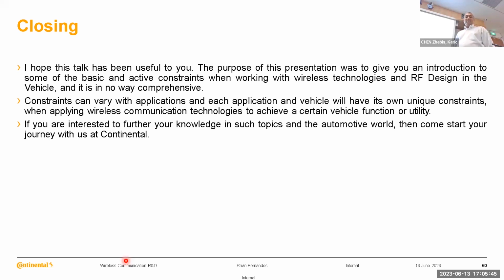Absolutely. There's very little we can do on the automotive side, because at the end of the day, GPS is designed as a function where there is a very high power transmitter high in the orbit, and a very high sensitivity receiver in the device. That receiver receives signals from at least 3 different satellites, knowing their position in the sky and their time of flight, and then makes an estimation of the position on the Earth.